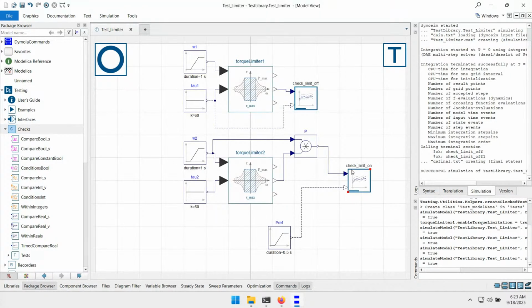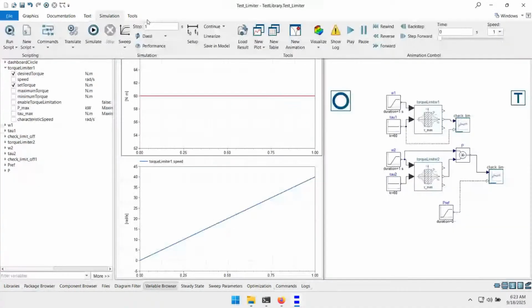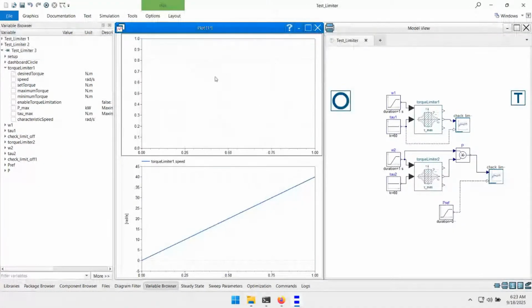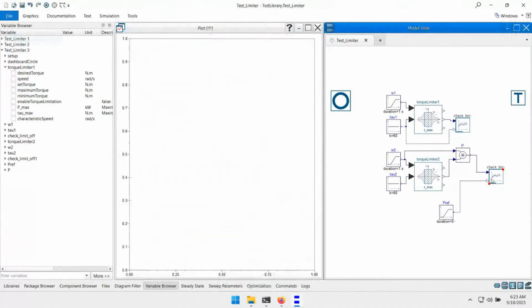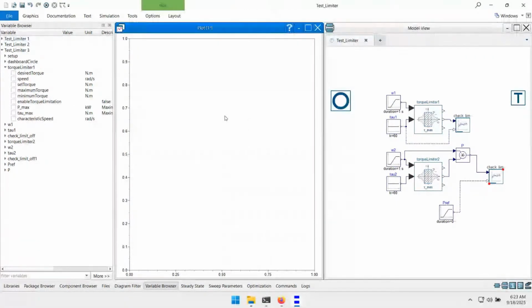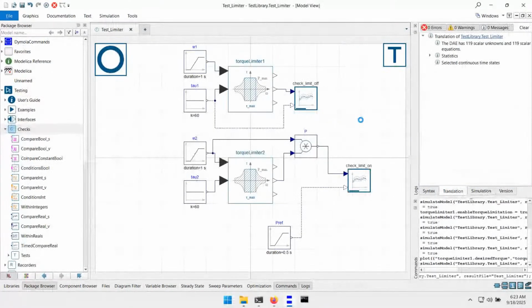And now let's look a little bit into details of what's happening. It's always good to check what you're actually comparing in your model. To do that, you can just go to the simulation tab and erase what you have here, and just click on this check block, maybe also delete this one, and then let me simulate again.